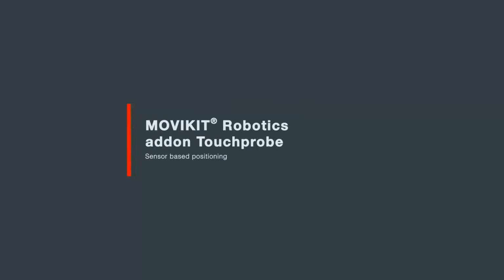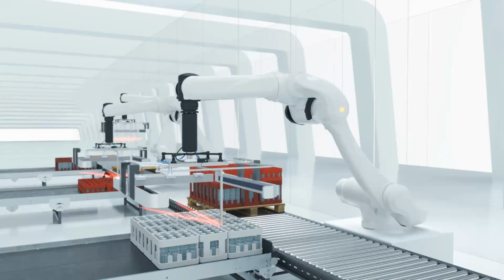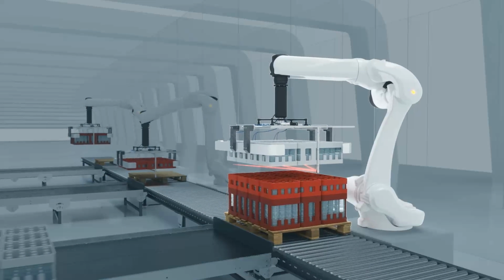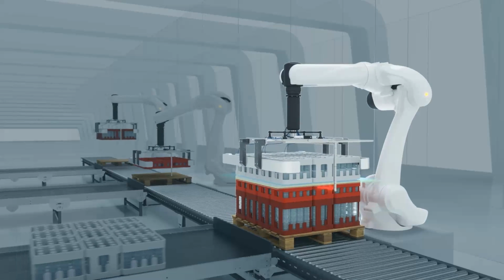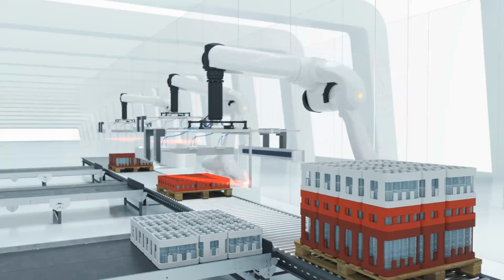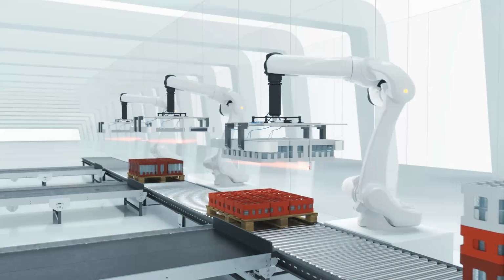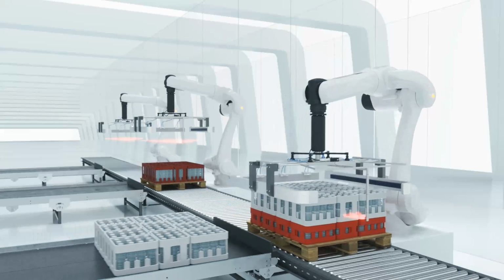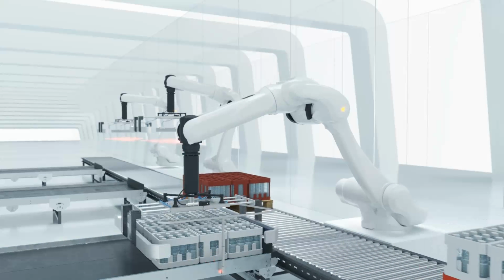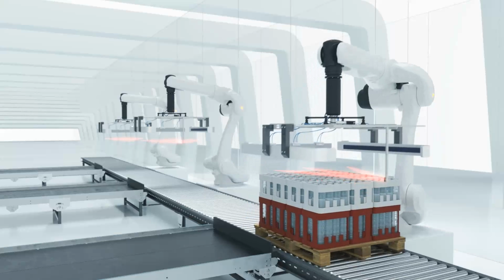With a Touchprobe sensor-based positioning, the top edge of the beverage crates is determined using a light barrier in the example shown here. Starting from this point, the robot then precisely travels a defined parameterizable distance to the pick or place location. The exact product or stack height therefore does not need to be known. This allows several layers of crates of different heights to be stacked without the individual robots having to know the exact height.